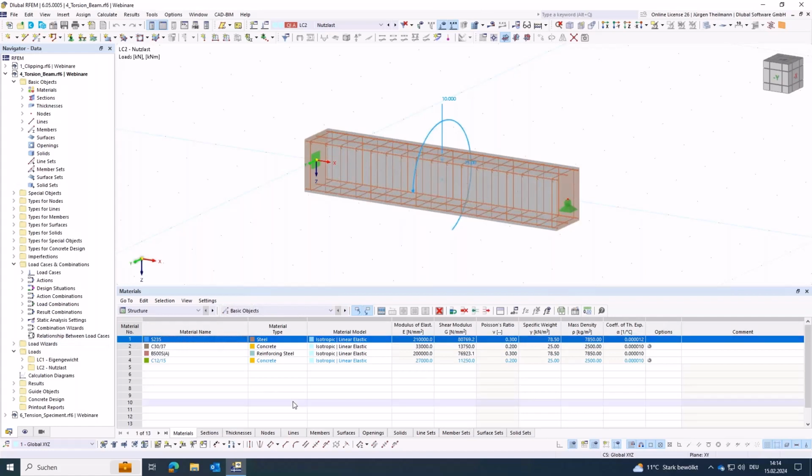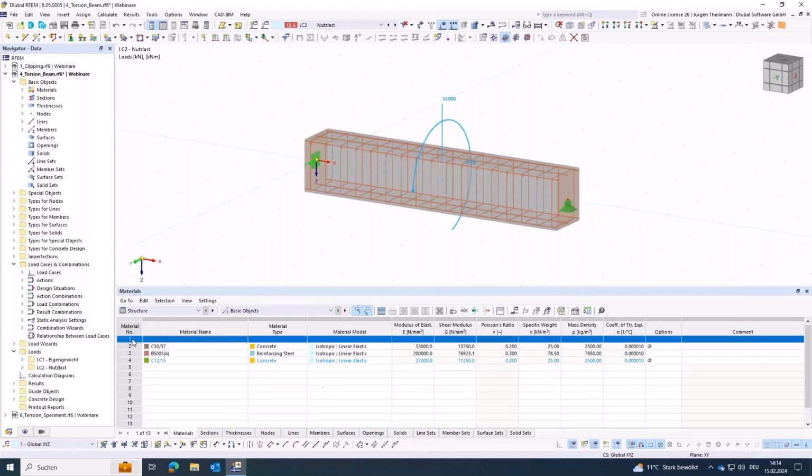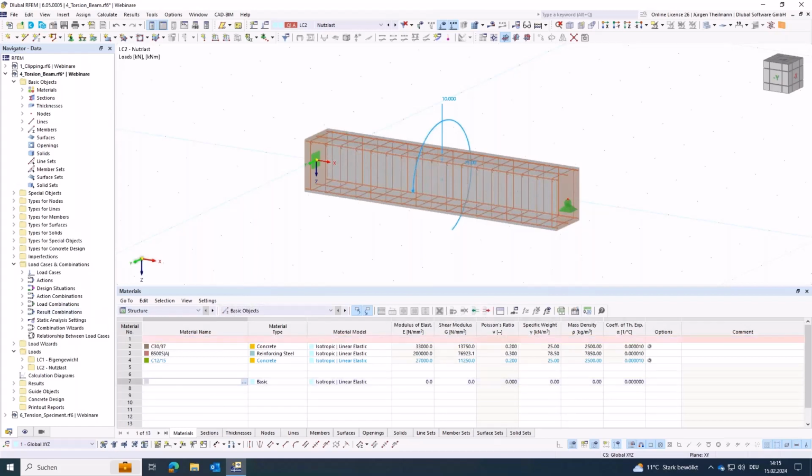So I go to material number 1 and hit delete to have the material deleted. Okay, now you see I have material number 1, which doesn't have a material assigned. But I don't want that. I want the material numbering to start at 1. So I go to this line and I want to delete it. But the button for this is grayed out, and with Control R, I also cannot remove this line. When I go out of the line, I see material number 1 is highlighted in pink. And that is a message from the program that you have something wrongly defined.